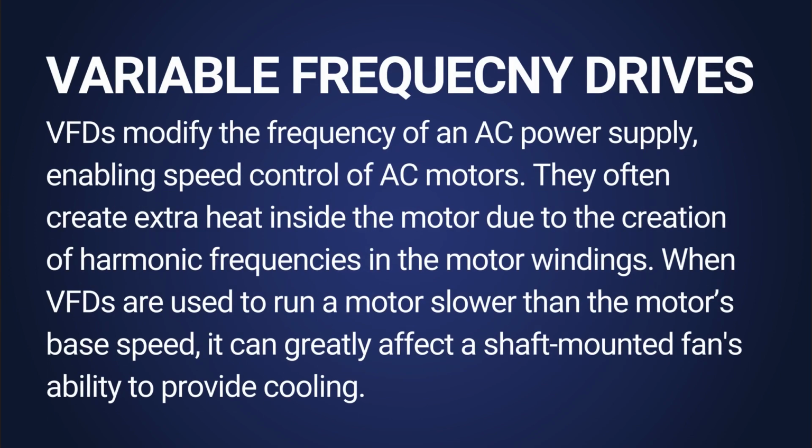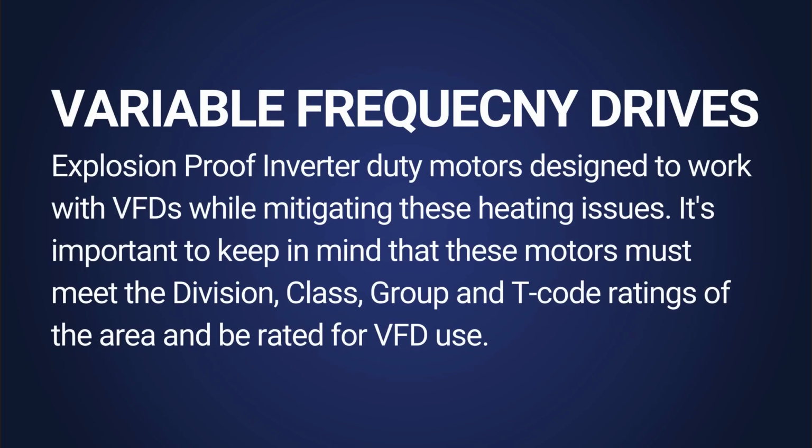An important point to note: using VFDs in hazardous locations. Variable frequency drives modify the frequency of an AC power supply, enabling speed control of AC electric motors. However, they often create extra heat inside the motor due to the creation of harmonic frequencies in the motor windings. Additionally, when VFDs are used to run a motor slower than the motor's base speed, it can greatly affect the shaft-mounted fan's ability to provide cooling. Explosion-proof inverter-duty motors are designed to work with VFDs while mitigating these heating issues. It is important to keep in mind that these motors must meet the division, class, group, and T-code ratings of the area and be rated for VFD use.